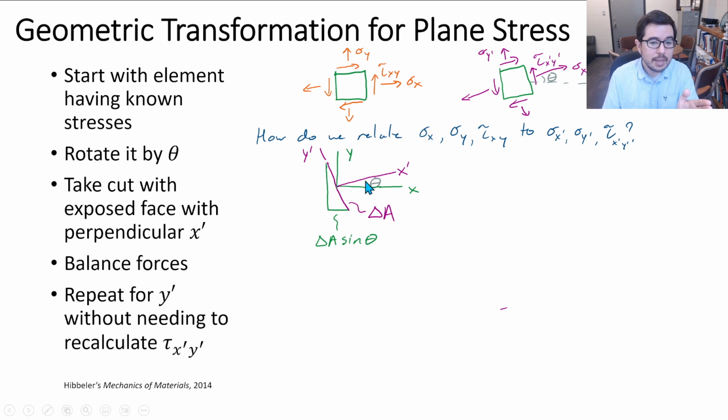So this theta is really in this corner here. And one thing I suggest, I'll say this a couple of times, and there's even notes here, is that when you draw these triangles, make them exaggerated. So even if theta is equal to 45 degrees, go ahead and say maybe it's really like a 15 degree, so that you can see theta would be in this corner, and this is going to be the opposite, which is delta A sine theta. And this one over here is going to be the adjacent, which is delta A cosine theta. So it's just a little trick to keep track of these things when we do equilibrium.